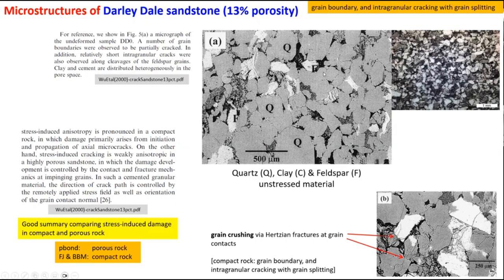And so you see these are cross sections, 500 microns. You can see the grains, and you can see weird stuff between the grains, and you can see porosity. This is a 1 millimeter length scale. This is what it looks like if you just hold it in your hand. And then you load it and it's crazy. Look at this. You squeeze these grains together. This one split. This one started crushing, and it's kind of fracturing, but it's a crushing zone, right? This is another good example, crushing. And so, again, oftentimes the rock already has this in it, okay?